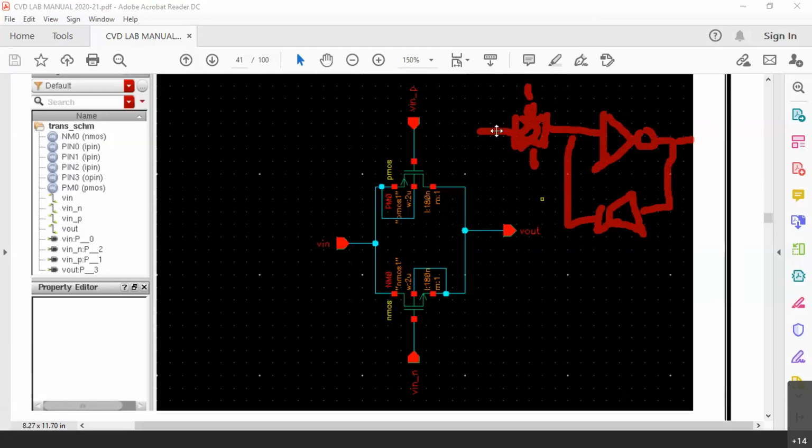Same way, using the transmission gate, the inlet of the signal can be controlled. Later on, the same signal can be stored by means of this particular cross-coupled inverter. If a weak signal is coming here, that weak signal will become strong by using the inverter here. The only point is you will have an inverted output, because if this is D here, you will have a D bar here. That logic state has to be taken care of in the design. Now this is one particular latch.